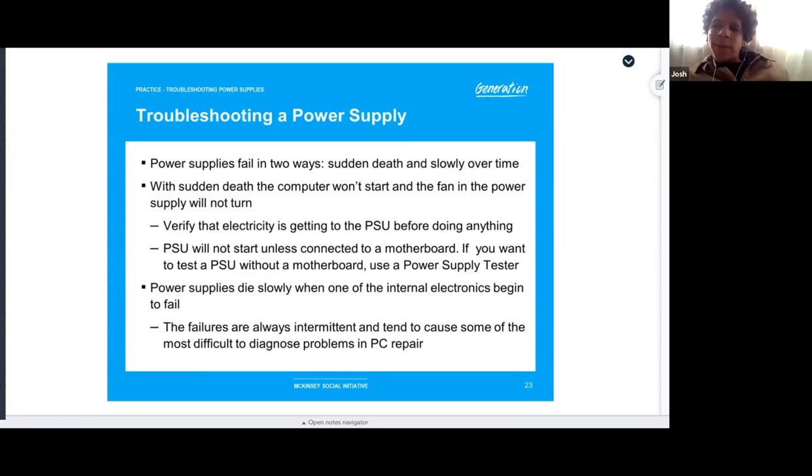Well, why was the answer false on the use of the multimeter in that quiz? Because he said to pop it open. He was popping the hood open. You're not supposed to pop the hood open. In the example he just gave you, you're actually going to go to the Molex connector and put in the two prongs, one onto the negative, which is the black wire, and one onto the positive, be it the yellow one for the 12 or the red one, which was 5. So you wouldn't open up the case.